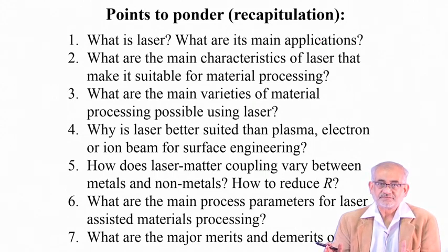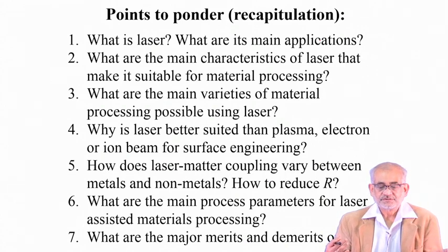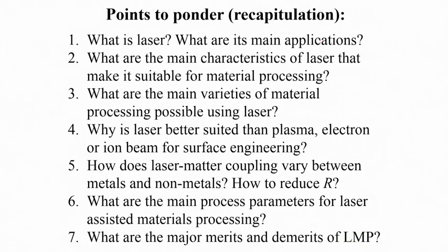The other side of the story is the material properties, which will involve the melting point, the density of the material, the specific heat, the thermal conductivity, and in turn which will determine the heat transfer coefficient. So all these will determine what is the thermal state, what will be the level and mechanism of thermal activation. What is good about laser is that the coupling efficiency is very fast. The way laser incident photon gets converted into lattice heat, it takes less than a nanosecond.